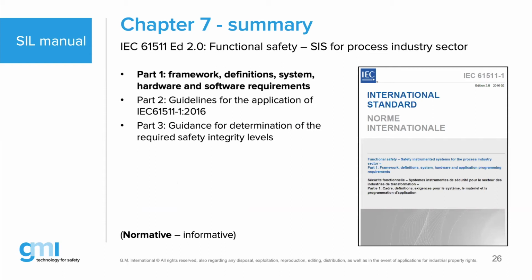You cannot self-assess, you cannot self-certify yourself, but you can have different teams. You have a good point, Paolo. As per the reasons for the 61508 requirement, a SIL 3 cannot make a self-assessment from the same company. It has to be from a third party or a different organization.